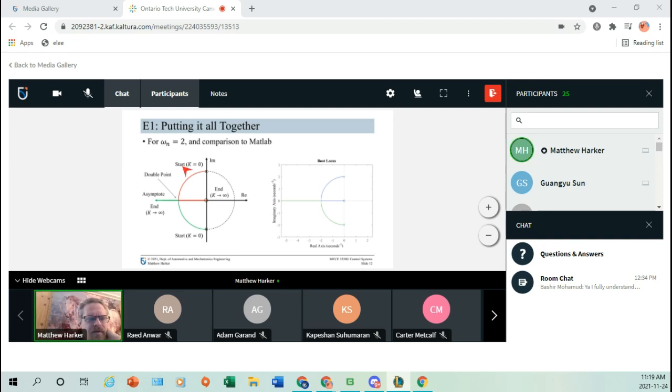So we have, as I said, starting point k is equal to 0. We're basically treating this as a set of parametric curves depending on the gain, or whatever parameter we're interested in. We should be able to extract any parameter where it's linear in our characteristic equation, right? So as we vary the value of zeta, in effect k here, is exactly what we got last time, right?